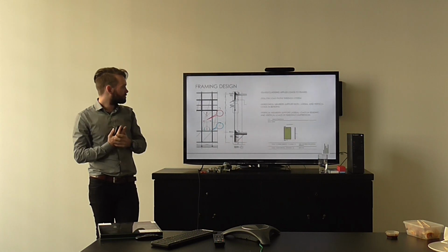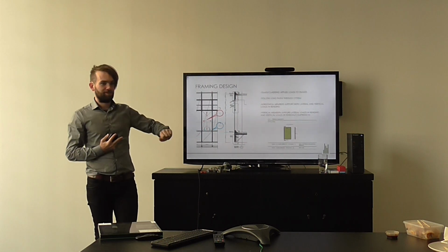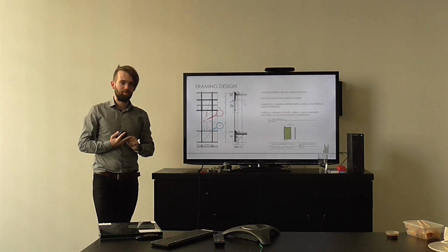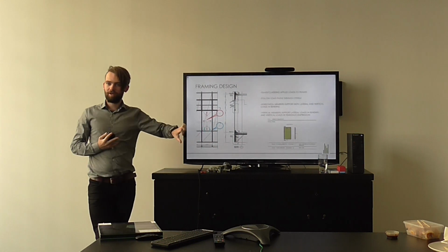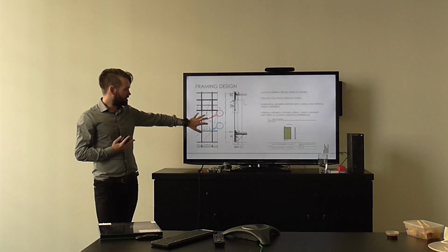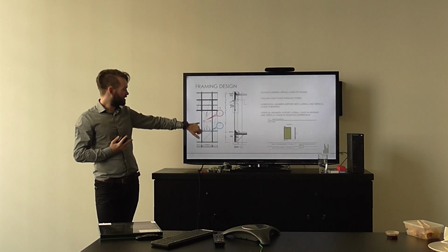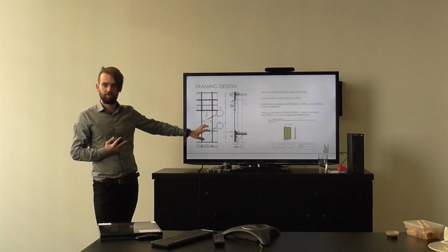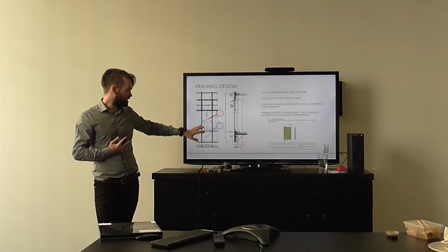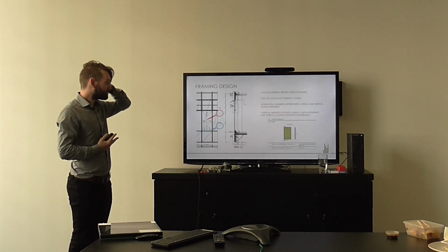Moving through our load path, as we spoke about before, now we get to our frame. So over here is a nice little curtain wall panel that was prepared earlier. Speaking on the load path we spoke about earlier, there are essentially two situations going on here if we look at this piece of glass. The wind hits the glass and is then distributed to the framing on four sides here, because we have a four-sided piece of glass, four-edge supported glass, and our dead load is carried through our setting blocks, as Alyssa identified earlier.